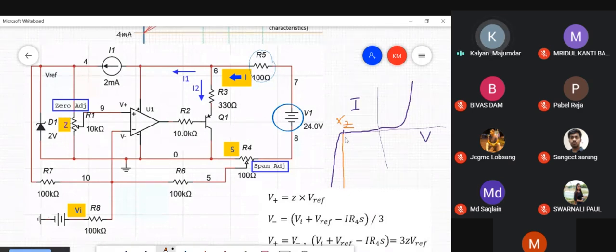But unfortunately, the reverse breakdown is something different. That means the voltage across the Zener is not strictly constant. It depends upon the current through the reverse biased diode, the Zener diode. So any changes in the supply voltage would cause a change in the current through the Zener if you use a resistance at this particular point, causing this reference voltage to alter.